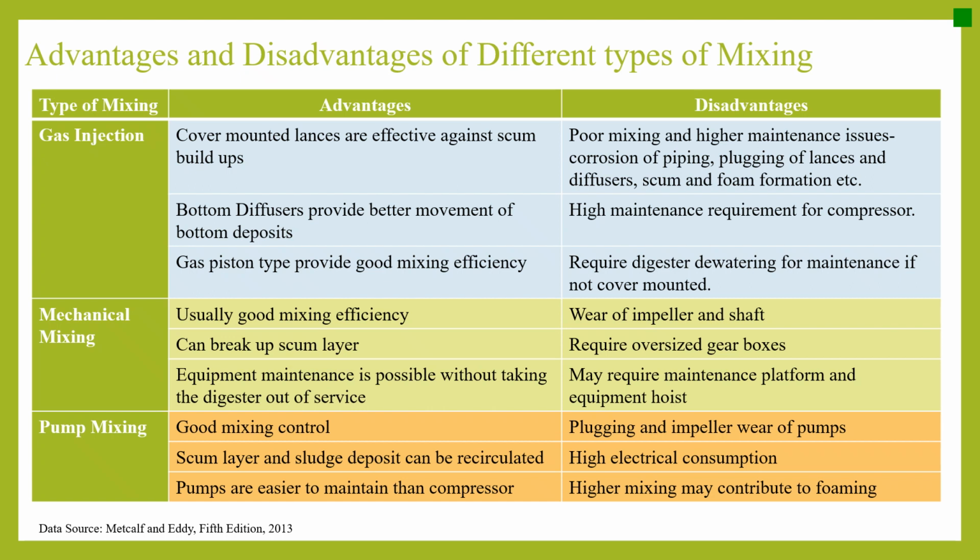Disadvantages: poor mixing and higher maintenance issues, corrosion of piping, plugging of lances and diffusers, scum and foam formation, etc. High maintenance requirement for the compressor, and it requires digester dewatering for maintenance if not cover mounted.